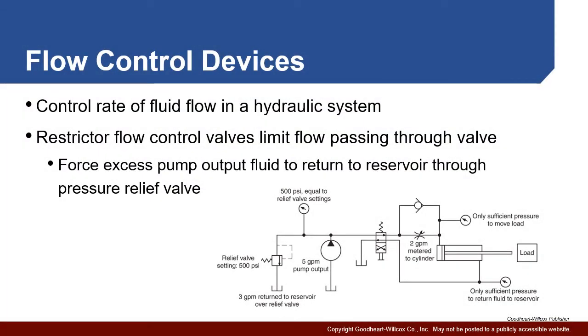Lastly, let's talk about flow control devices. They, of course, control the volume of flow in a portion of the hydraulic system. They are essentially different forms of restrictors in most cases. So for example, if you take a look right here, this is a flow control device. You see the symbol looks like it's being squeezed off or closed off. And that's essentially how a flow control device works.